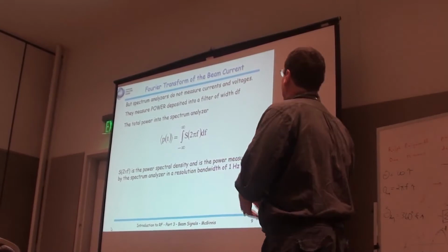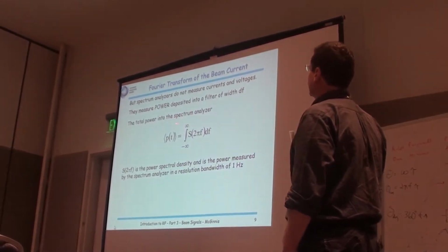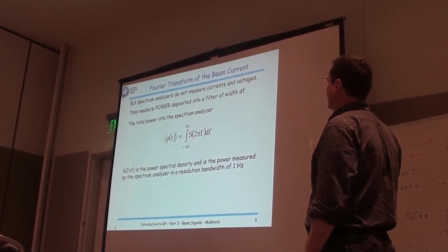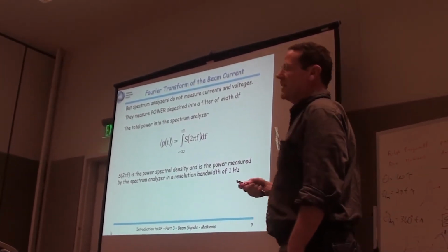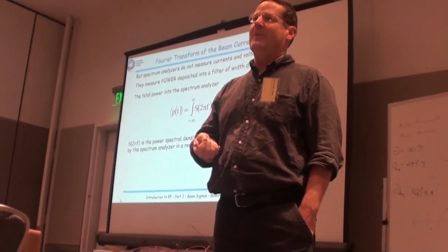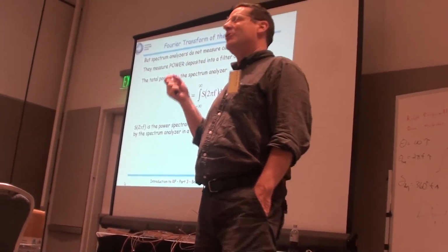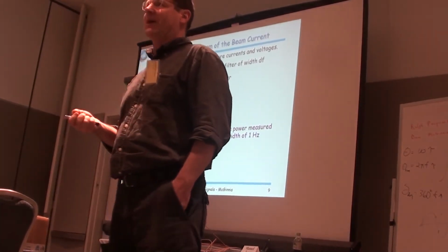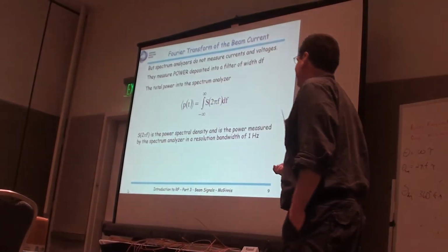So for the total power into a spectrum analyzer, you would integrate the power density over frequency. So what spectrum analyzers really measure is not power per hertz, they measure power spectral density, which is power per hertz. Excuse me, I misspoke here.